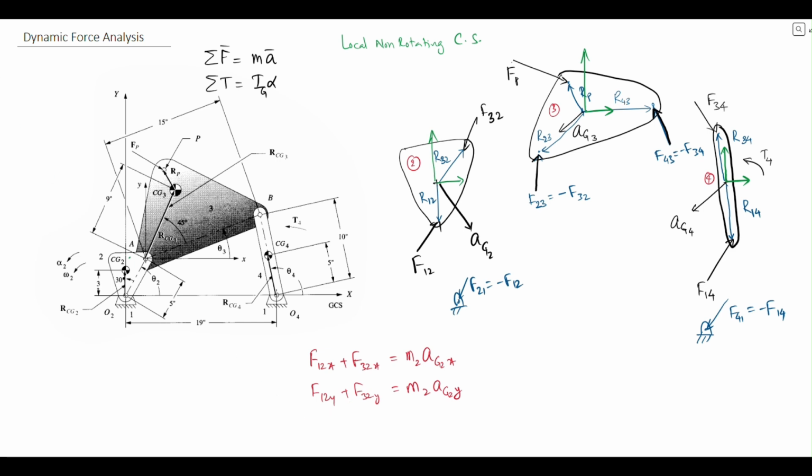Then we can write the torque equation similarly. If we are considering body number 2, you have a torque T12 which will act to ensure that there is dynamic equilibrium against these forces Fp and T4. So we have to assume that there is a torque T12, and maybe we'll assume it to be a positive torque. Then as we proceed through the computation, if we find it has a value of, say, minus some numeral, then we can adjust the direction accordingly.